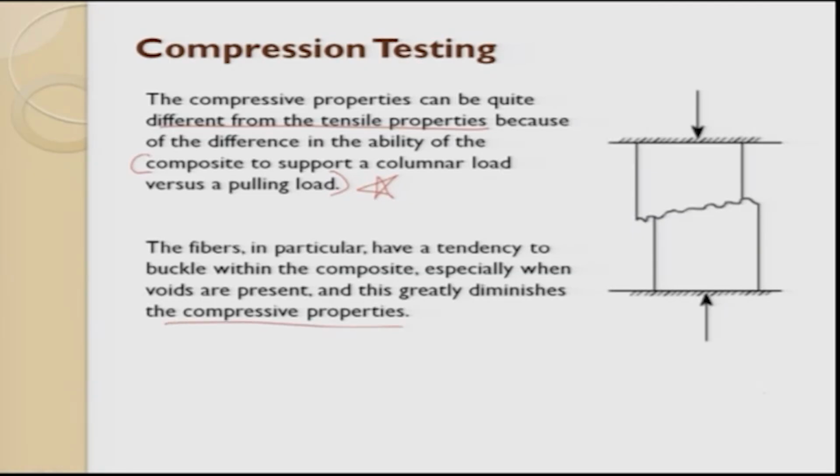One important thing you should all remember is that only a sound product should be used for testing. If there are voids or holes because of processing difficulty, they will yield very fast.